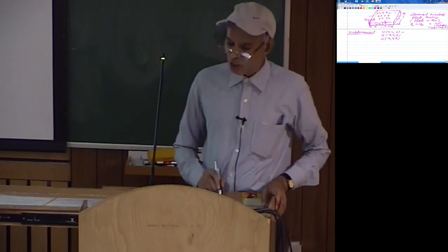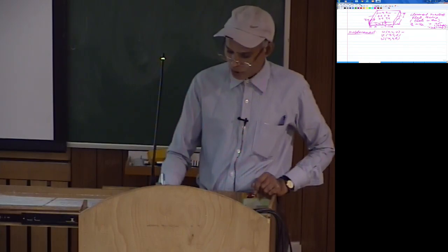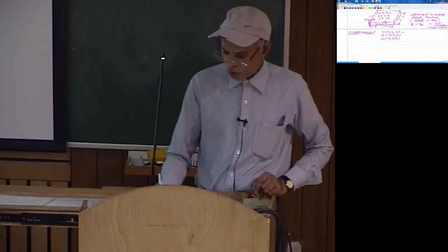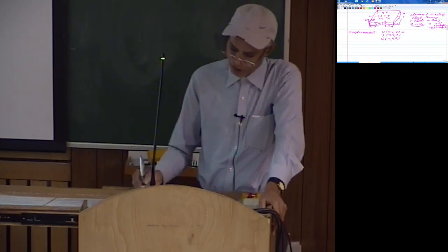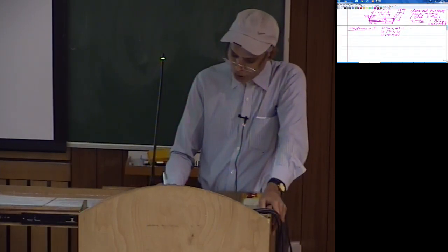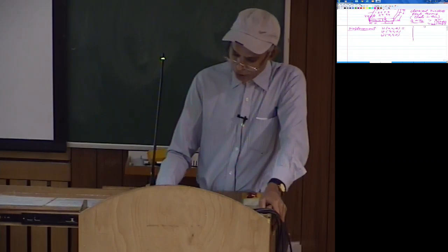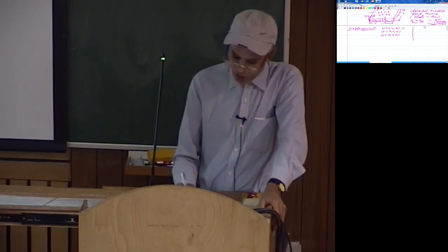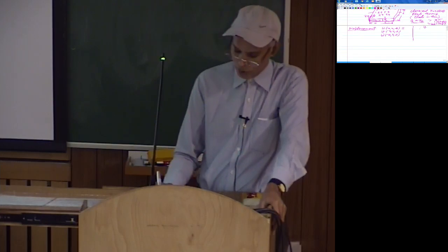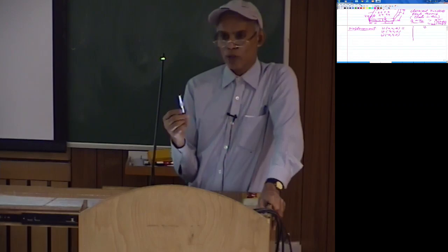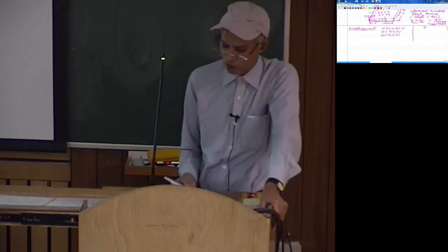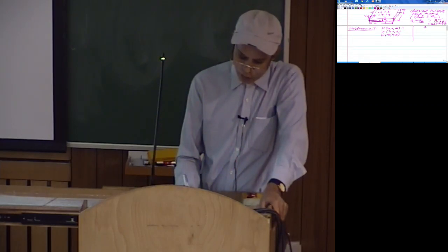So this is basically one assumption. If the plate dimensions are according to this, then you can use what is known as classical Kirchhoff plate theory. And in this, what you say mainly is that normal to the mid surface. Now here you have a middle surface. Like in the case of Euler-Bernoulli, we have said that normal to the neutral surface remains normal after deformation. So similarly here also you talk of this normal.